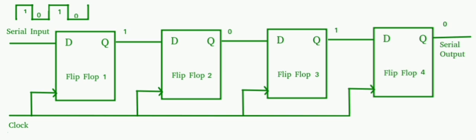HTL: basic gate NAND, fan out 10, power dissipation 55, TPD 90 nanoseconds, figure of merit 5000, noise margin 4 to 5 volts. TTL: basic gate NAND, fan out 10, power dissipation 12 to 22 milliwatts, propagation delay TPD 12 to 6 nanoseconds, figure of merit 144 to 132, noise margin 0.4 volts.